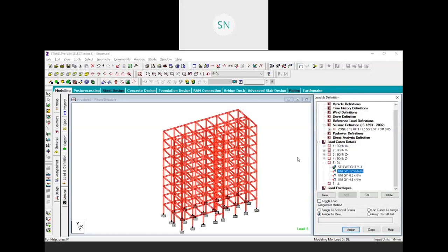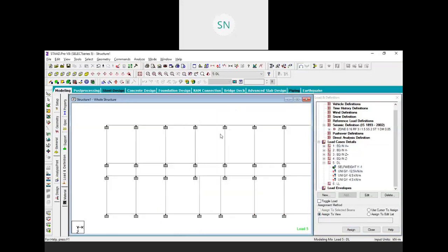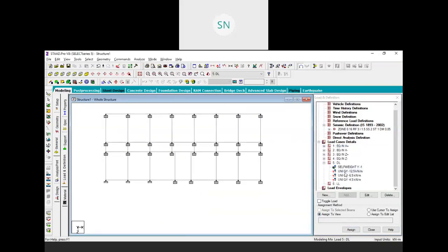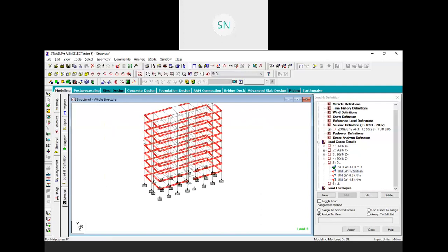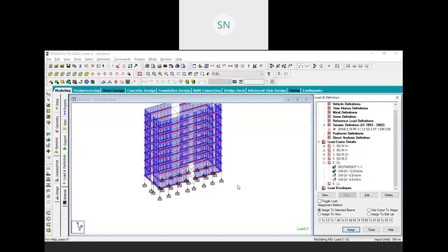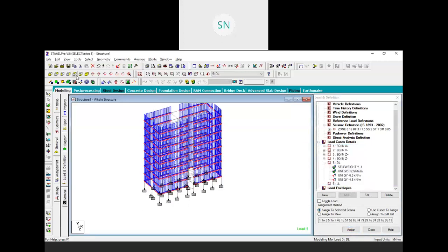then this wall load, so that will be from the top, 9-inch wall, like this. See, if you view it from isometric view, we have selected all the boundary walls, right? So click on the 9-inch wall load and click on assign, and yes, so we assign 9-inch wall load.